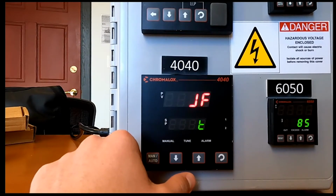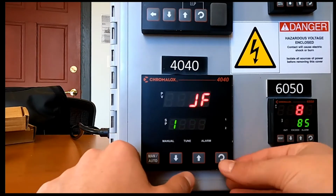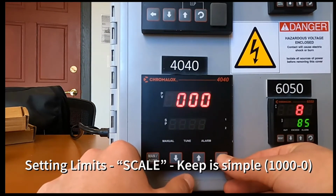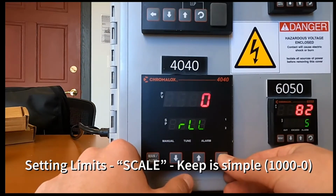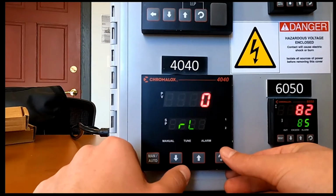So the first thing that happens is I go into the sensor selection, which in this case would be a J-type thermocouple with the engineering units of degrees Fahrenheit. And then you have to hit the manual auto button to keep it. The next two steps would be the scale range upper and lower limits.